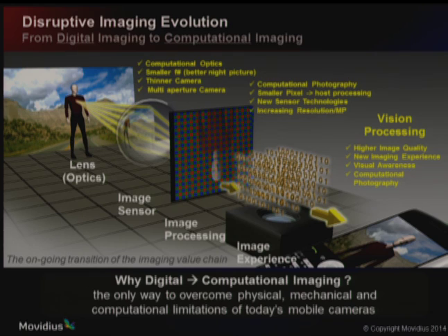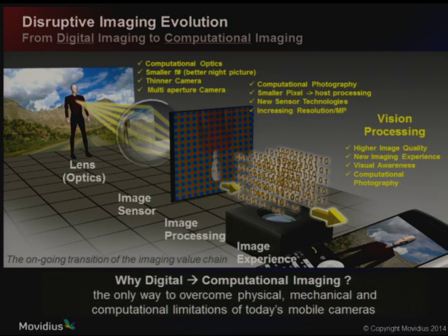And you need to basically take all of that data, collate it, extract feature points, extract metadata, and uplink that over a MIPI interface to an application processor that then runs Android and the Android HAL and basically does GPU rendering for things like VR. So essentially here you're talking about an area where it's very difficult to boil everything down to hardware. You essentially need a highly capable, flexible, software programmable platform to deal with the degree of change that there is